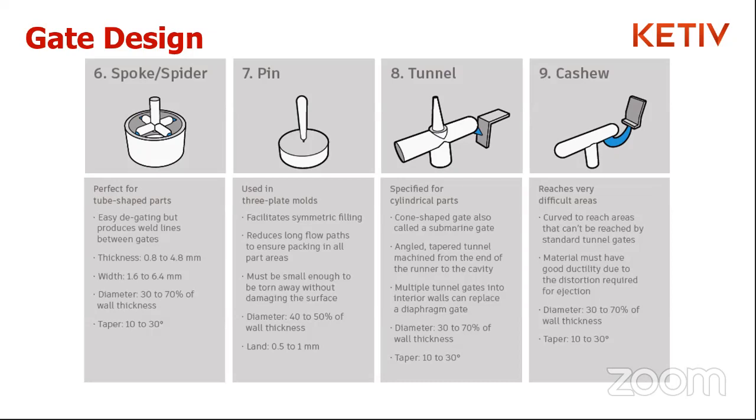If you look at just tunnel gates in this slide here, there's at least a half dozen to a dozen different forms of tunnel gates to explore that some folks actually consider one having advantage over another. And there's some merit to that and data that you can create based on simulation. But this is just one small function of a mold in process that extends through the process, fill, pack, and into cooling or solidification, that impacts cycle time, part quality, performance.